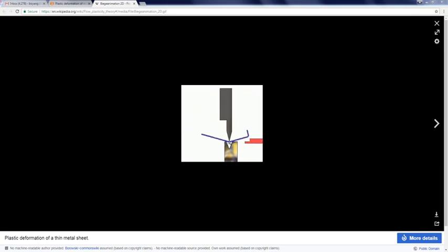So you see that the thin metal sheet is being pushed down by the indenter, held against a base, and then because of plastic deformation, the metal sheet stays more or less in a deformed shape, with a small amount of elastic spring back after unloading. And the loading was controlled perfectly such that after spring back you have a right angle here. So today we are going to try to use Abaqus and try to reproduce this right angled hook.